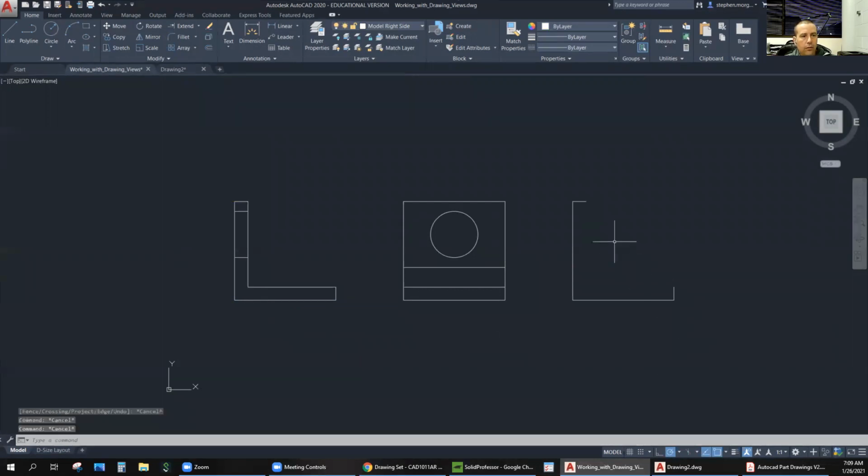Okay. In order to get the radius in here, what we're going to use is the fillet tool, sketch fillet right there. Down here, it's going to give you options for how you want to describe the size of it. Usually in a fillet, we're going to use this radius command. So we're going to give it a radius value. Here, the R is blue. That's to show you what letter to type. So I'm going to say R, enter.